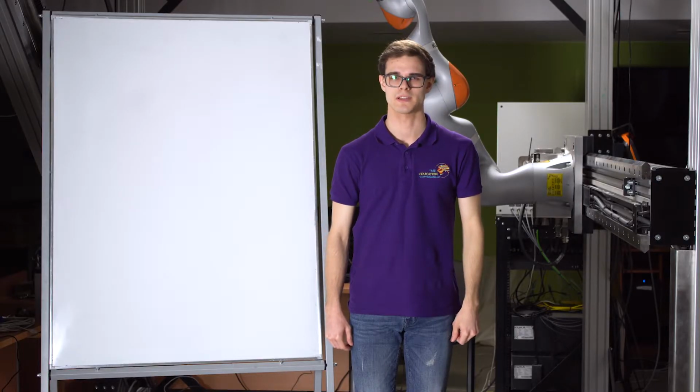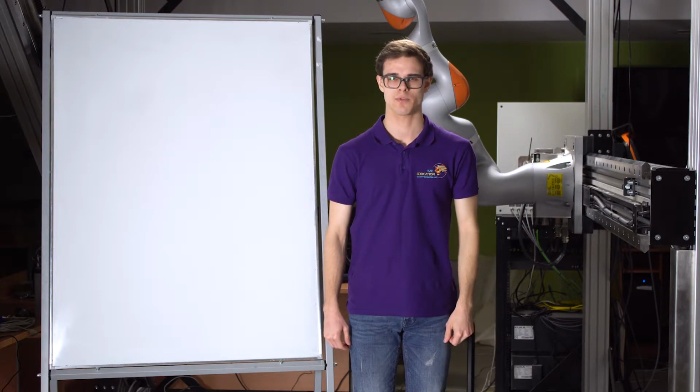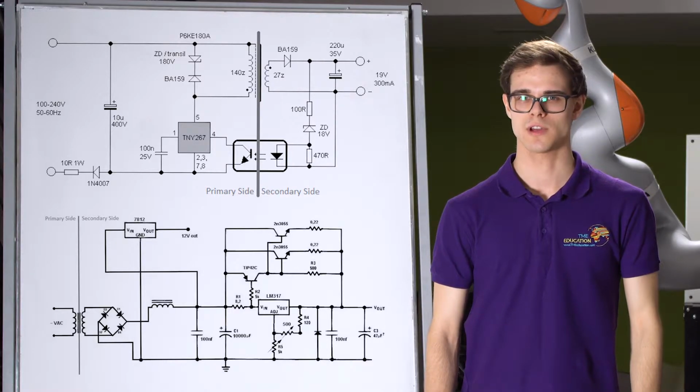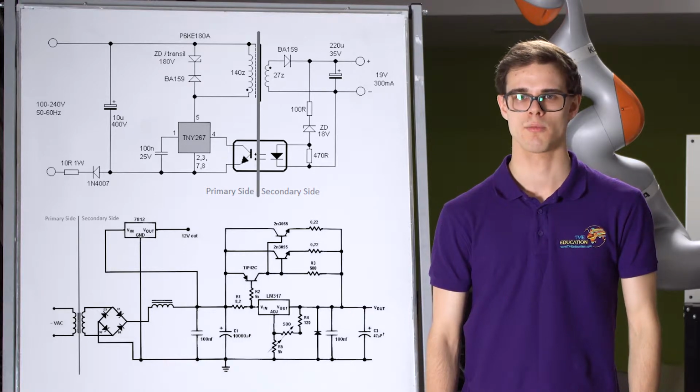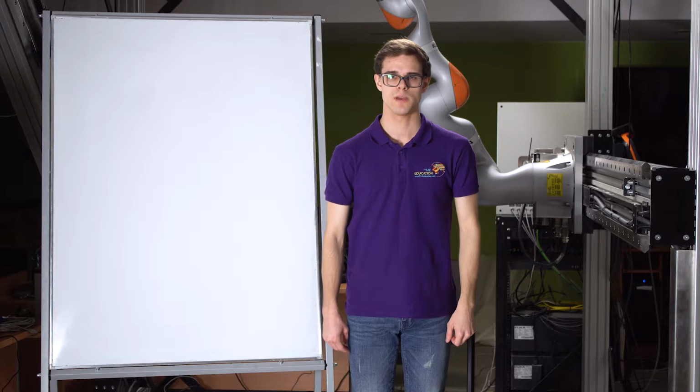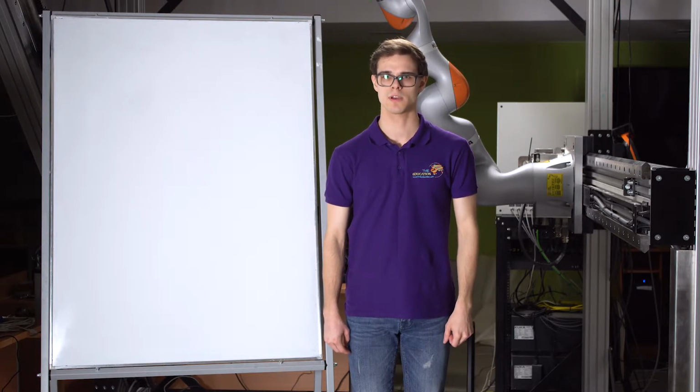Most of power supplies have a so-called galvanic separation. This solution allows to transfer energy and information in forms other than electric current, such as optically with optocouplers or magnetically with transformers. This solution prevents from electrocution from the electricity network because potentials on primary side are not related to the potentials on secondary side.